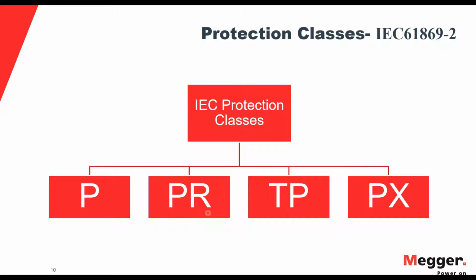Then we have the BR, the low remanence classification of the B class. And then we have the TB classes, TBY, TBZ, TBX. In these classifications, the T represents the transient behavior allowed in these CTs, as we will see later on.